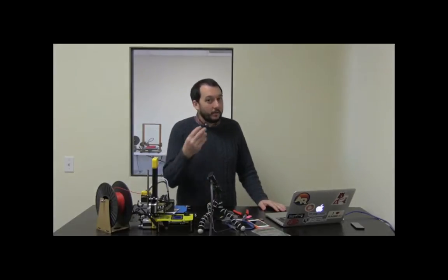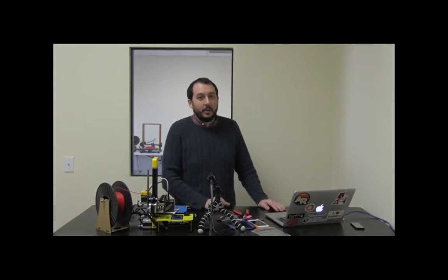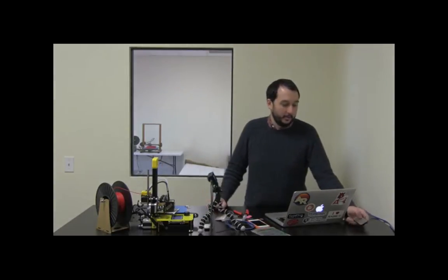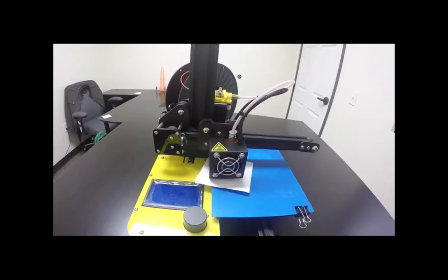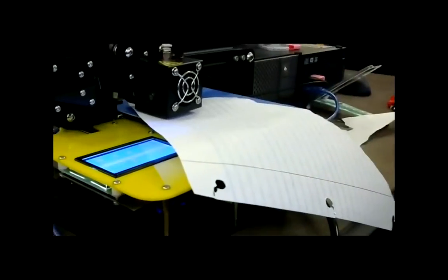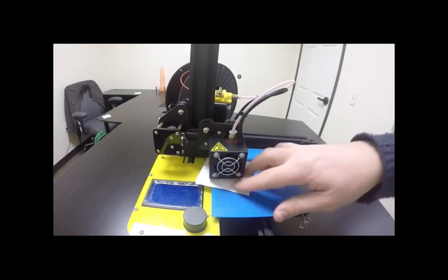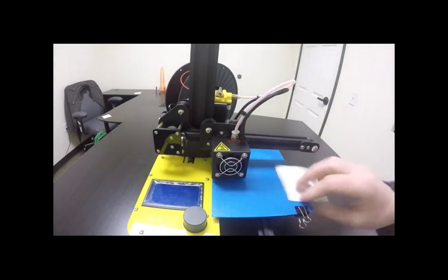And those are all 4 of the troubleshooting steps. So once you have those figured out, you'll be able to be cranking out prints in no time. Sweet. Does the paper move? Yeah. Okay, awesome. Then pull the paper all the way out, and then go ahead and go back and print your Squirtle. You're good to go. Do we need to auto home before we do that? Nope, it'll automatically home before it prints Squirtle.